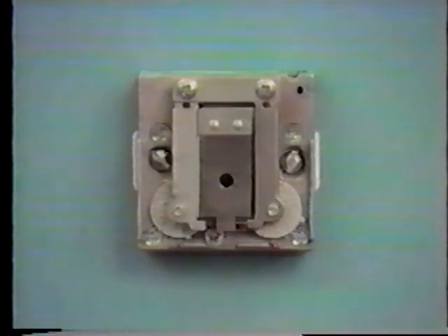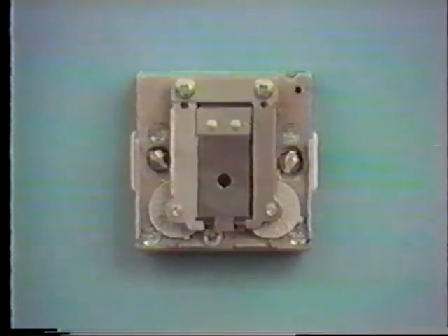This thermostat differs from the standard pneumatic thermostat in that it has two set point adjustments. It is a single pressure device which offers separate heating and cooling set points and a single branch line output. This type of thermostat is used where an individual thermostat controls both the heating and cooling function. The throttling range of the thermostat is divided up or split between two set points. A dead band is created where no heating or cooling energy is used. The width of this dead band depends upon the heating and the cooling set points of the device.